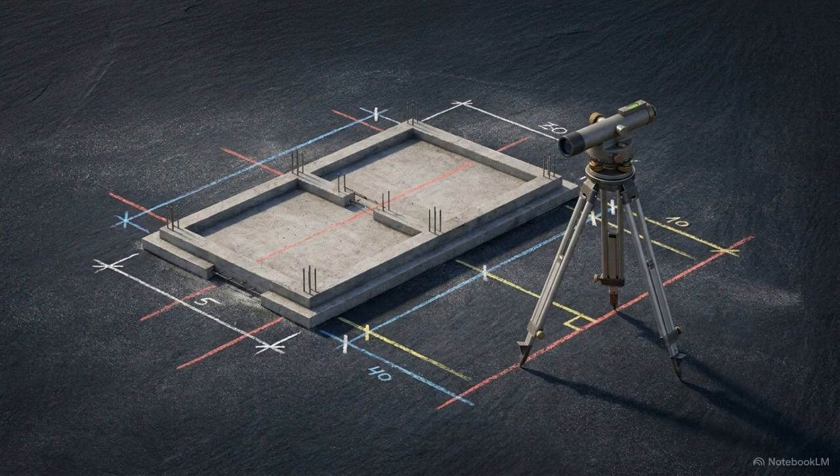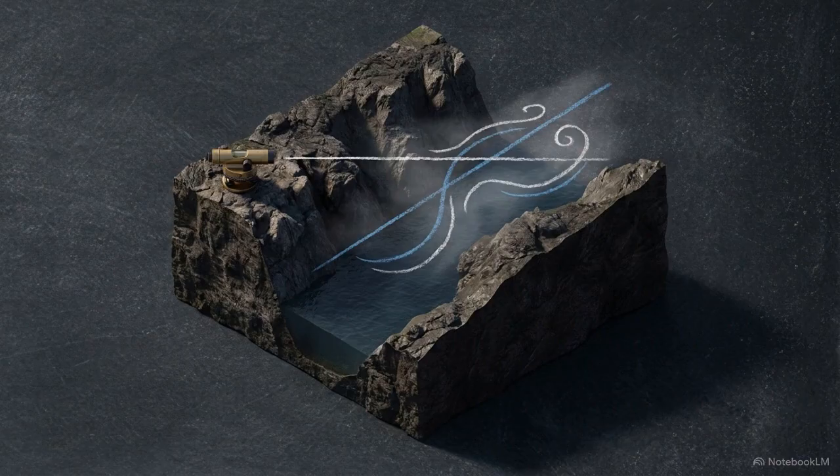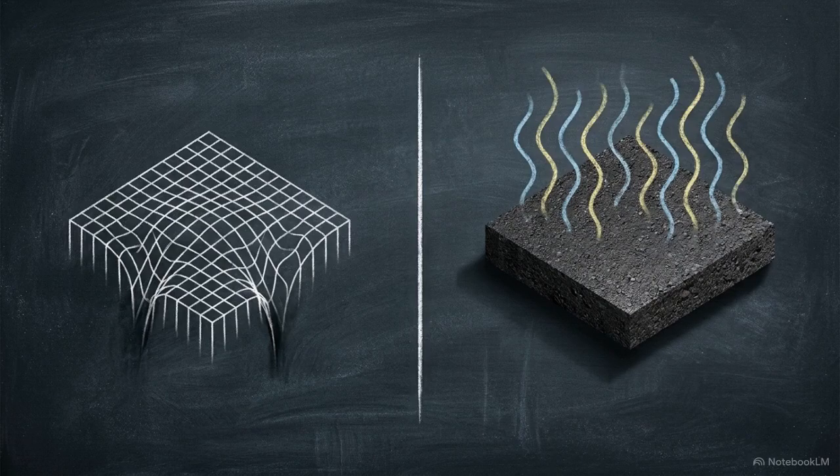On a standard construction site spanning a few dozen meters, this curvature error is mathematically negligible. But when spanning a valley or river, this geometric divergence completely invalidates the raw elevation data. Curvature is only half the problem. As light travels over those same long distances, it encounters a second major environmental distortion, atmospheric refraction.